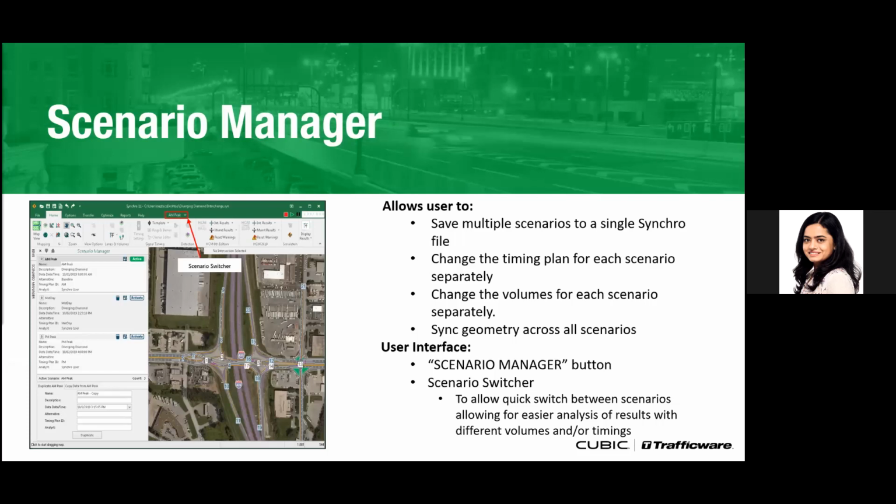Like with the older version of Synchro, like version 10 or 9, you had just the exact same network, but because you have different volumes and different timing, you needed to maintain multiple different files, and errors with multiple files are very common, right? We saw that and we hear you, and that's why we brought the Scenario Manager. Now, Scenario Manager allows you to save multiple scenarios to a single Synchro file.